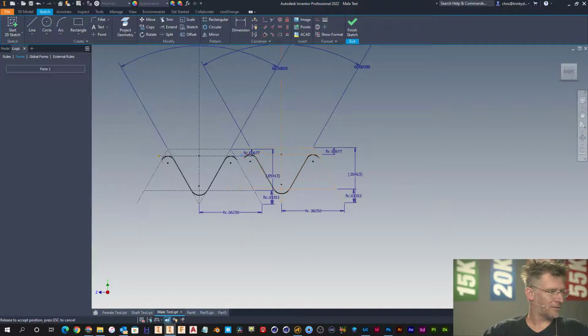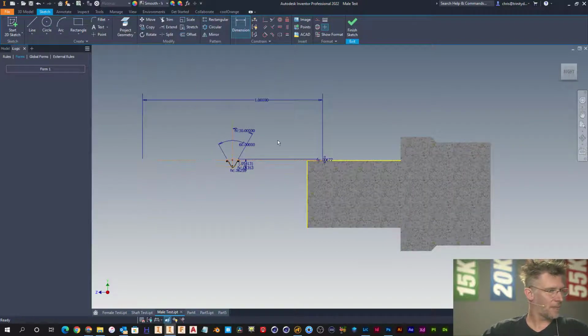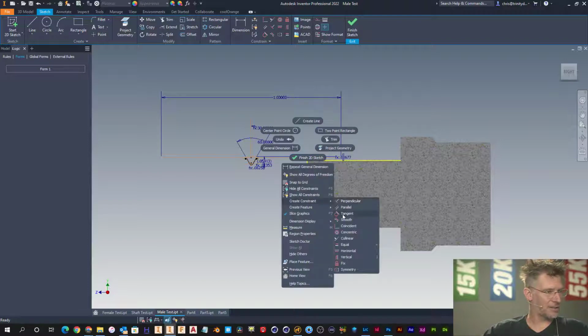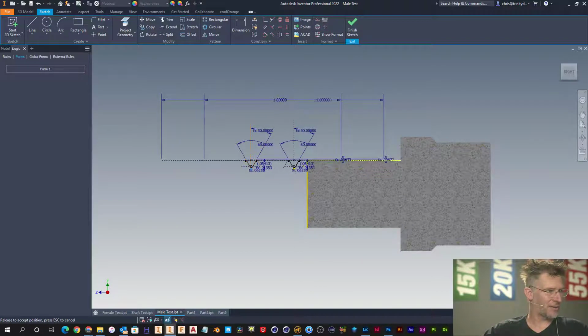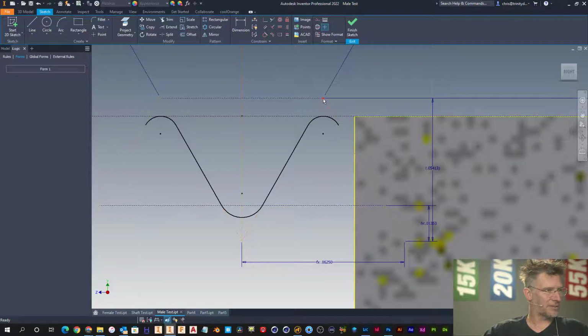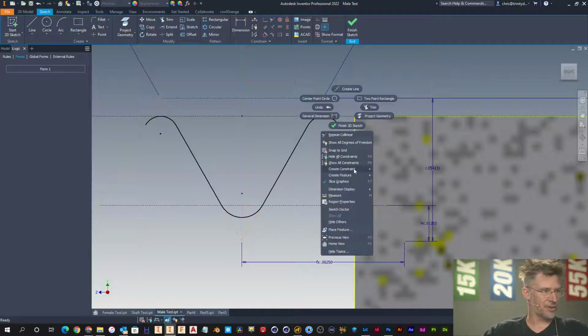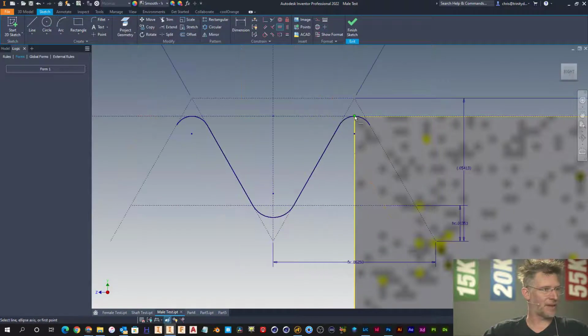There, now I can drag this around, and then we're going to call this line here, we're going to just say that's like 1 inch. There. Now I can kind of drag it around and I can see what I'm doing. So I know that I want that line to be collinear with this line. There we go. Now I'm free to kind of drag this around. And what we want to do is get this point in line with that. So let's do another constraint, a vertical or a horizontal constraint. We want that point in line with that edge.